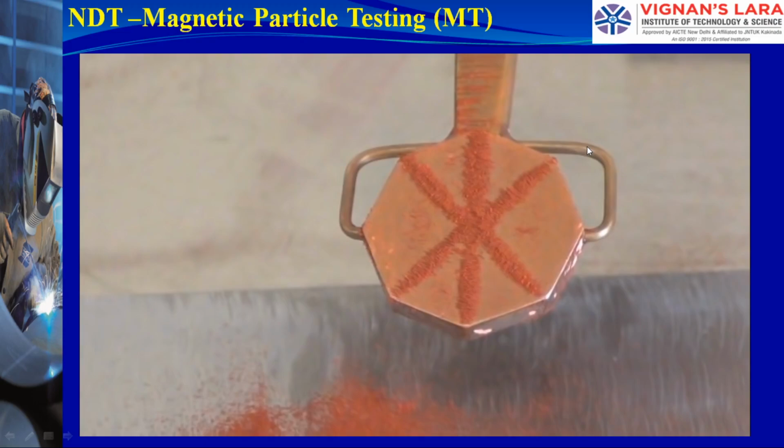And then I'll go to the second plate, do the same process, apply the magnetic field, sprinkle the particles, and then remove the excess particles from the plate, and the indication shows up very clear. Here is the indication, and the length of the indication in this case is 22 millimeters. Again, it's right there, and it's about 22 millimeters.